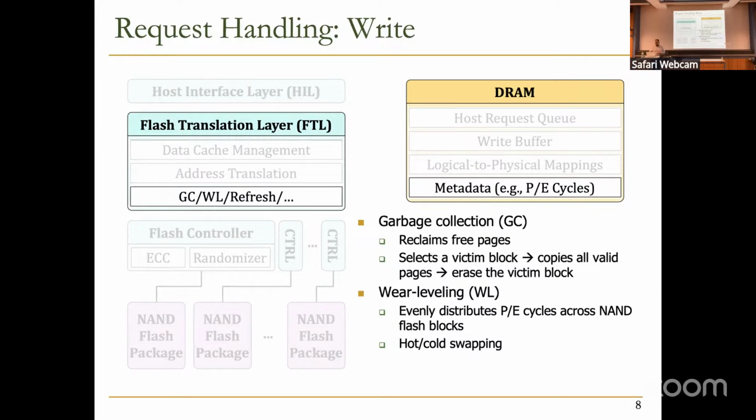And it's quite easy to implement in flash memory, right? In SSDs, because you can easily remap the logical address to another physical location. But this might not be that easy, for example, in DRAM. Think about RowHammer: when you are accessing one row, remapping that row to another location is not that easy, because that logical to physical location procedure is not implemented that thoroughly inside the DRAM chip.